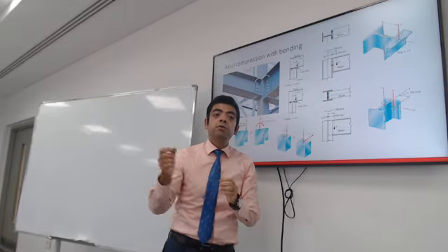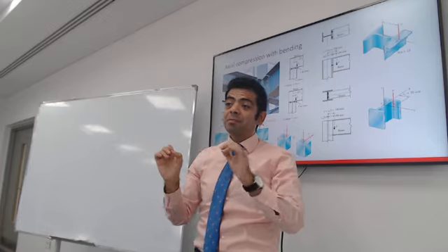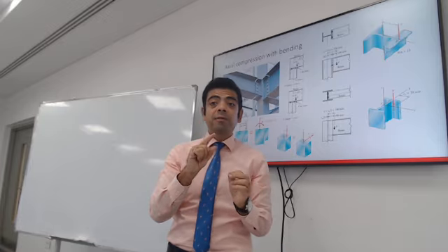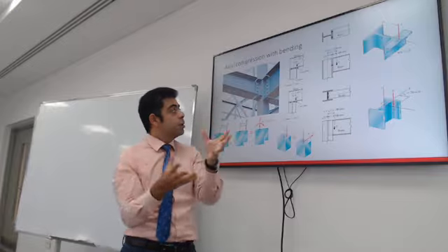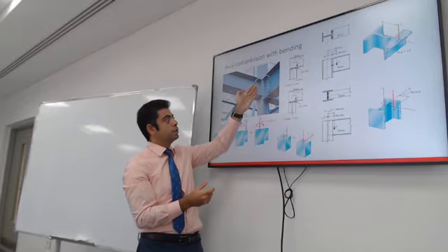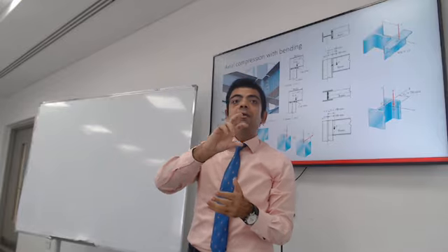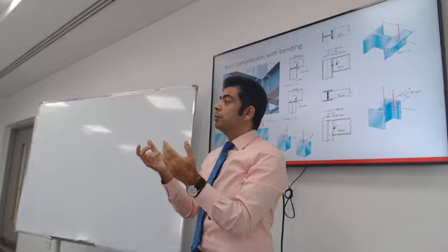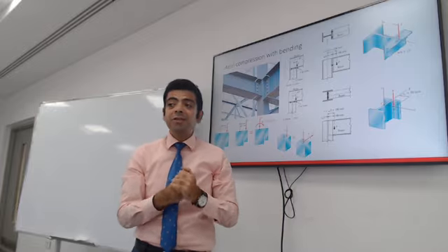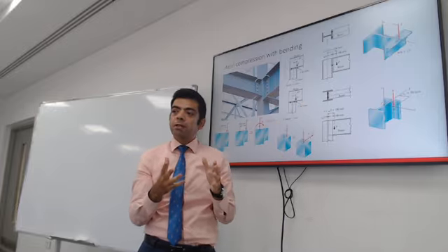And we will use the vertical load from the beam calculation, the reactions of the beam calculations, multiplied by the geometry of the connection. How far the bolts are going to be from the center line of the column, and we calculate the moment on the column, and it could be in both directions. Do you see how the eccentricity could be in both directions of the column?